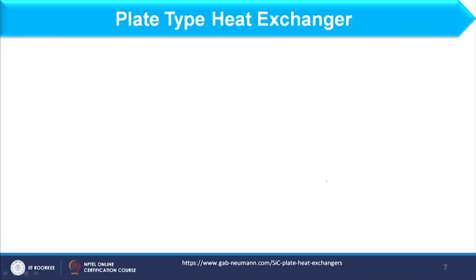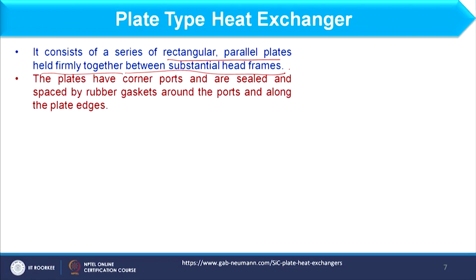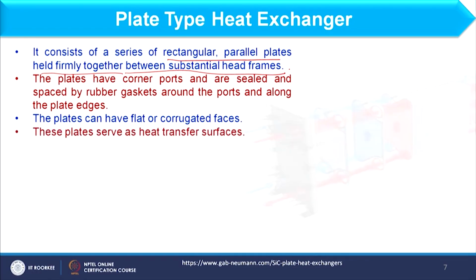Now, let me focus on plate type heat exchangers. Okay. As we have tube and shell in shell and tube heat exchangers, here we are dealing with plates. Okay. So, it consists of a series of rectangular parallel plates held firmly together between a substantial head frame. So, here you see in the plate type heat exchanger we have the head frame that I will show. Okay. Let me show that first.